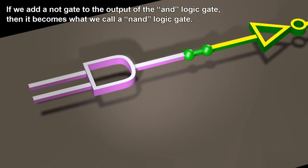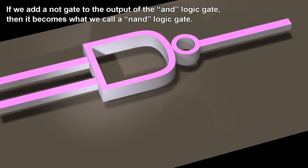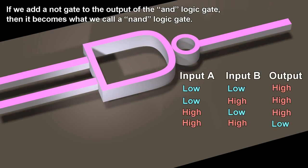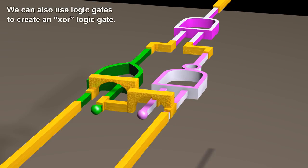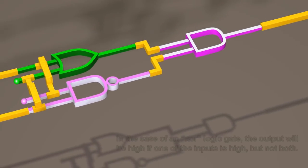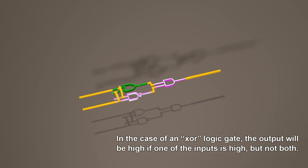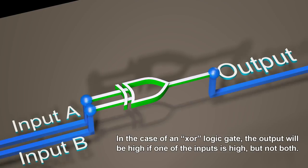If we add a NOT gate to the output of the AND logic gate, then it becomes what we call a NAND logic gate. We can also use logic gates to create an XOR logic gate. In the case of an XOR logic gate, the output will be high if one of the inputs is high, but not both.